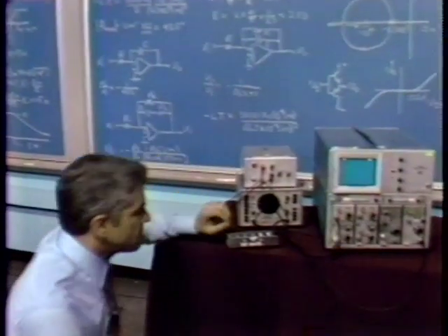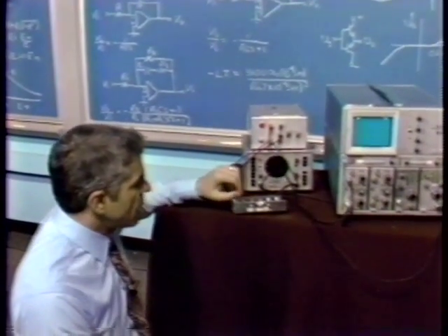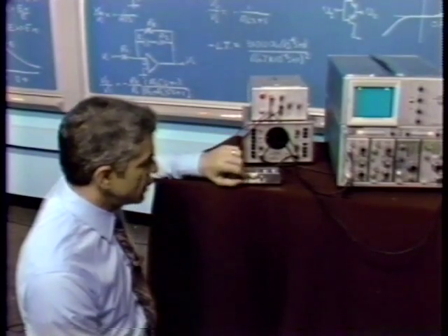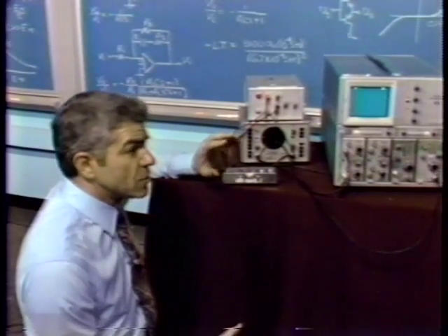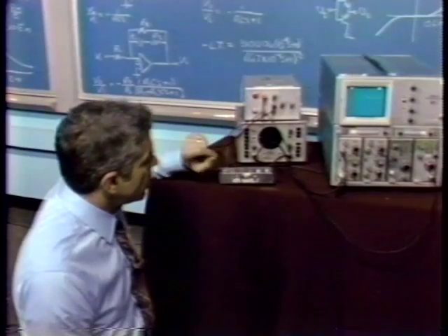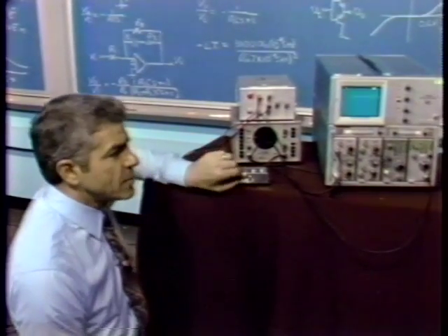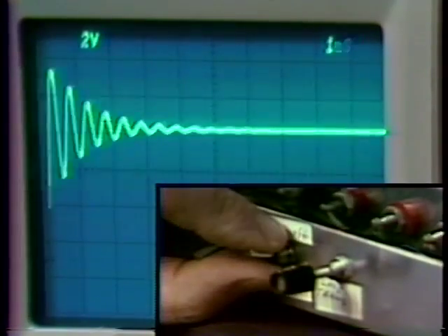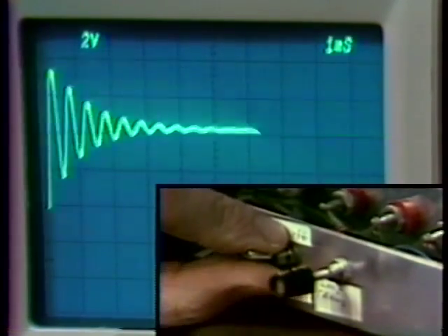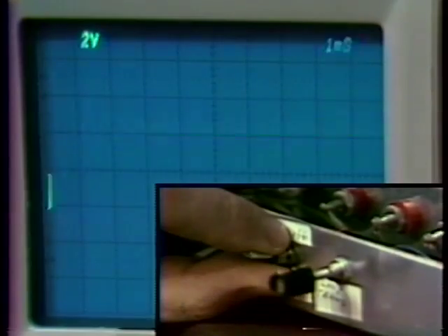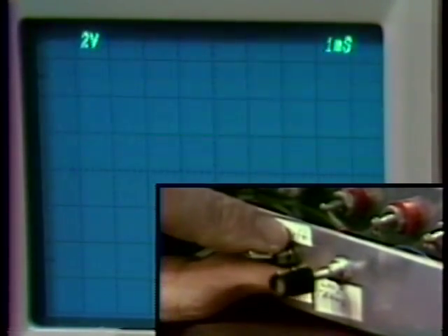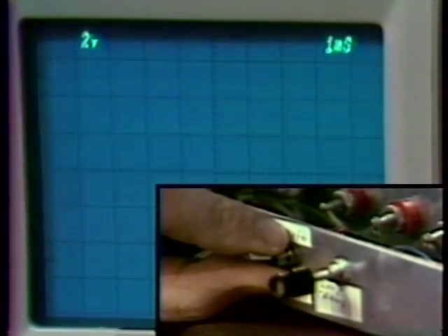The kinds of arguments we made looking at what happens as we increase amplitude, and seeing if the system is conservative or restorative, are reversed, and now the high frequency crossover point becomes the stable amplitude oscillation. Furthermore, we get into trouble with this system with too small signals rather than with too large ones.